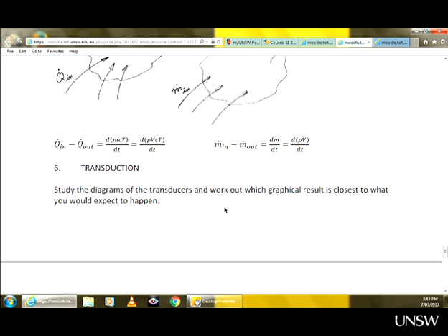The usual thermal power of a human is about 120 watts, times how many people, so that is also heat in. So the sum of all rates of heat in minus the sum of all rates of heat out will show whether this room is cooling or heating, whether the rate of change of heat is positive, negative, or possibly zero.